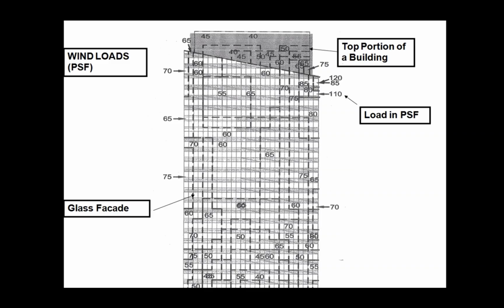Okay, and what you'll get is a report, something like this, that comes back that will show you where you take the most wind load. And obviously you might have to build a more robust section or reinforcement in that section. And then you also use these results to factor back into your design and figure out what you need to do to accommodate this. Will you need something to rebalance the building? Will you have that shock absorber type system somewhere on the top floor? Or can you build without that and just rely on the structure itself?